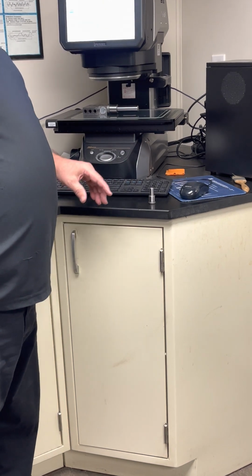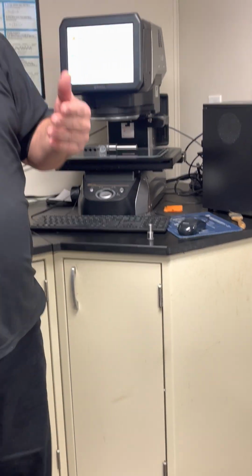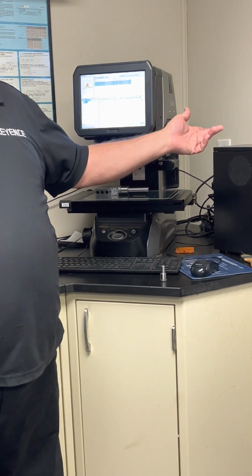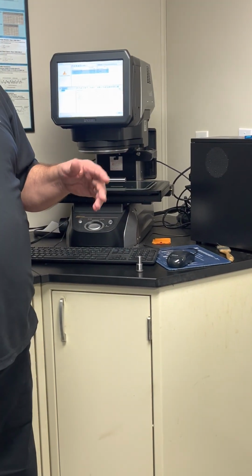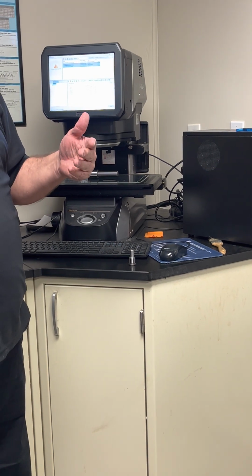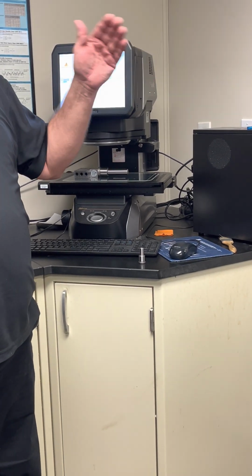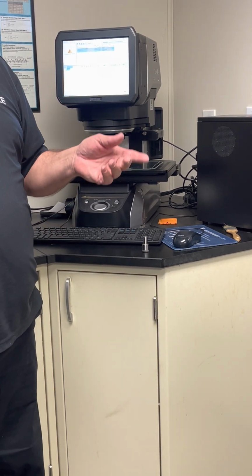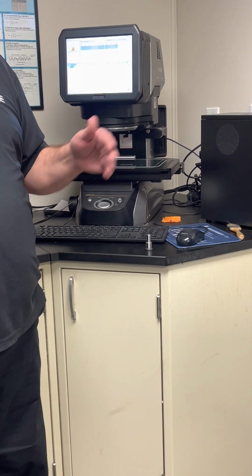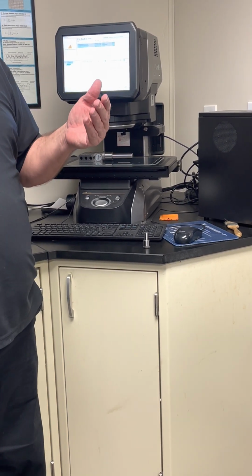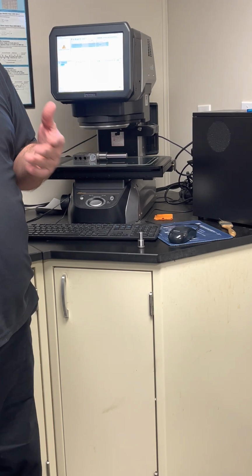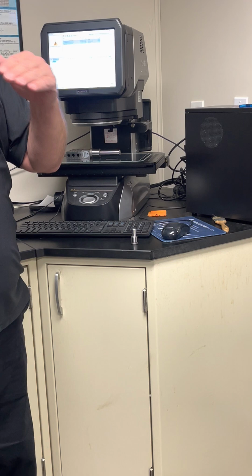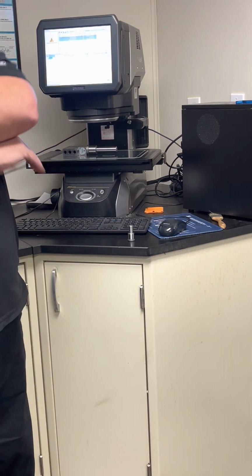Now what I can do is I have offline programming that basically mirrors all of this programming. So now I could open that up. Again, everything would have to be either online or through a dongle. But now I could open that up and put all my lines in, put all my tolerances in by sitting at my desk. The only thing I cannot do sitting at my desk is change the focus or change lighting, because you're working off of a picture at that point. But if you actually do two focuses, you're going to have two layers, so two pictures really that you're working with.